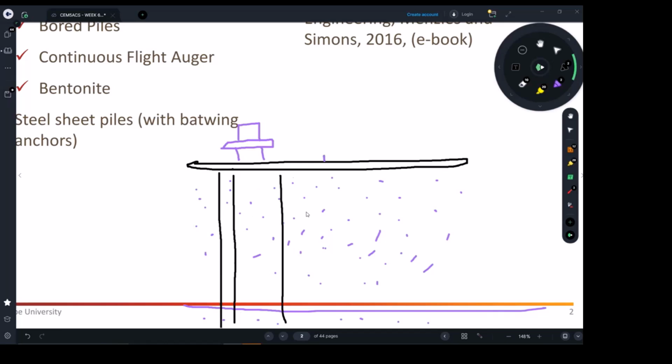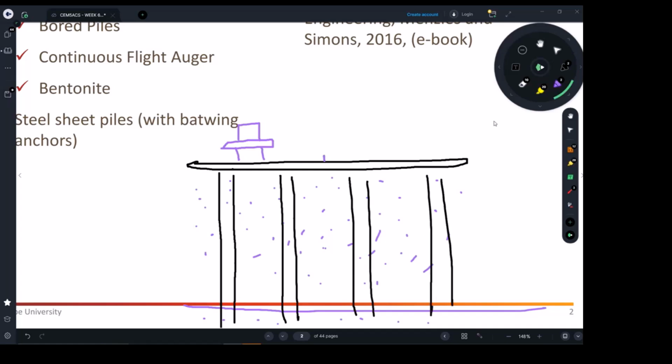So they're going to be every maybe 2 meters. And then on top of that, we're going to build a suspended concrete slab, I'll put it in purple. It's just going to be a concrete slab reinforced with top and bottom reinforcement. So effectively, your system is just suspended slabs sitting on columns, and each needs to take, as we said, thousands of loads. Then the engineers will be designing a concrete slab to suspend trucks and all those loadings. It's like a flat slab.